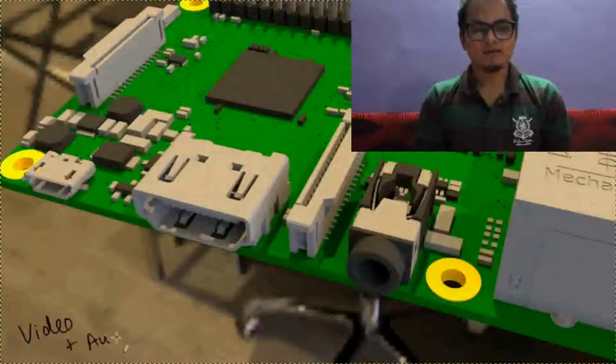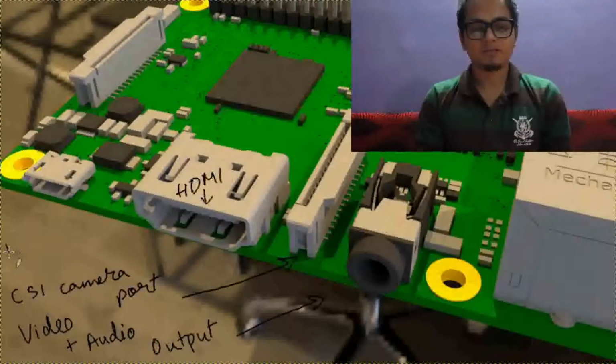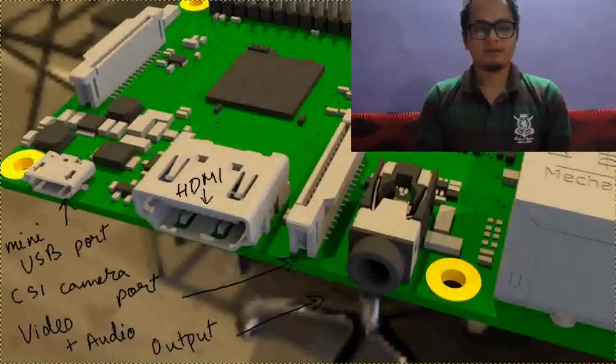Moving on to its side, we can notice the 3.5mm 4-pole composite video and audio output jack. And just beside it, we can observe the CSI camera port through which we can connect the Raspberry Pi camera module. Next to it, we can see the full-sized dedicated HDMI video output through which display devices with HDMI input can be connected. Also, we can see the 5V over 2.5 ampere DC power input to power up the whole module.